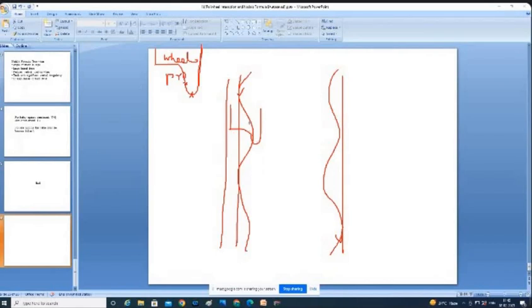Suppose it goes this side, this side will be a little far, it will go like this. Suppose it is going here, it will go like this. Like this you have to imagine. So from this you have to understand that the path traversed by the wheel set over the rail table is of a sinusoidal motion, not a straight motion. It is called a sinusoidal motion.